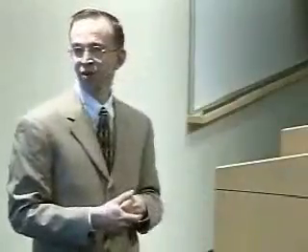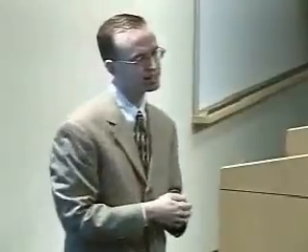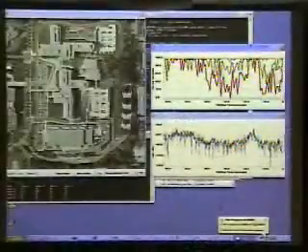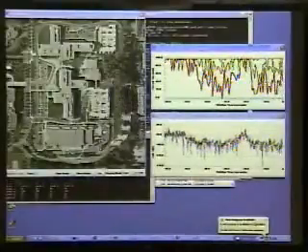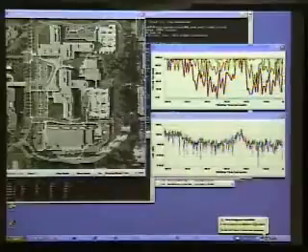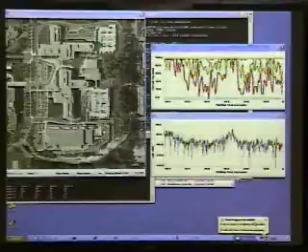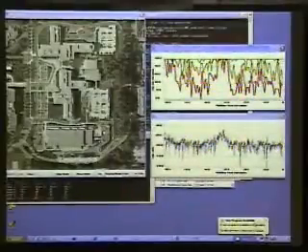In particular, we were talking about moving the Rician and Rayleigh fading models into the FPGA. If you're recording, that would probably need to stay out. There is a bottleneck there in how often we can update. For 4 nodes, it's basically no issue. When we get to the full 15 and you have over 200 of these channels that you need to update, then I think we'd still be under the microsecond, if I remember this calculation correctly. But we want to push as much of that down there as possible to offload the PC.